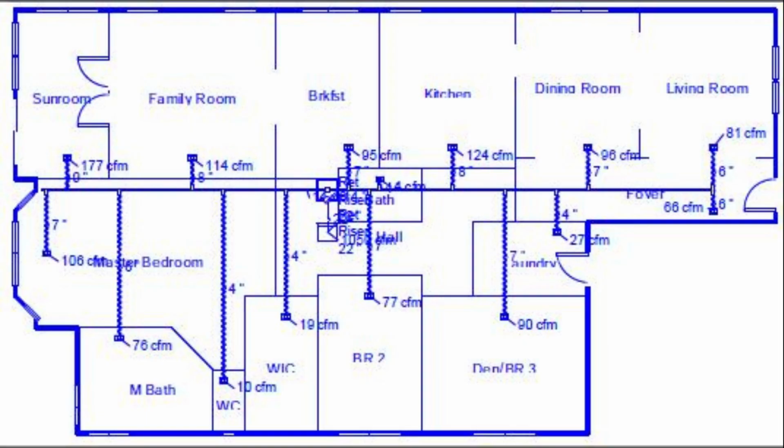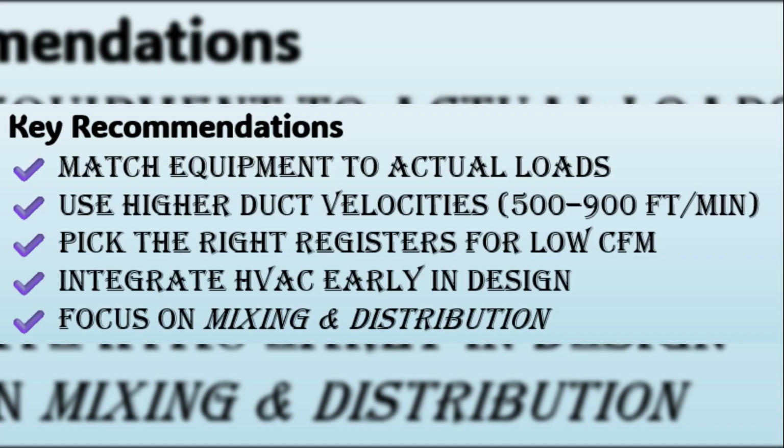Flex duct installation. Stretch flex ducts out to full length and avoid kinks and compression. Duct location. Install ducts in conditioned space, either in an insulated non-vented attic or crawl space, or buried in attic insulation. So what's the bottom line?